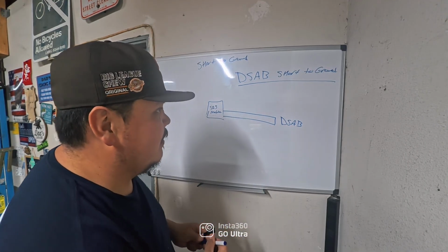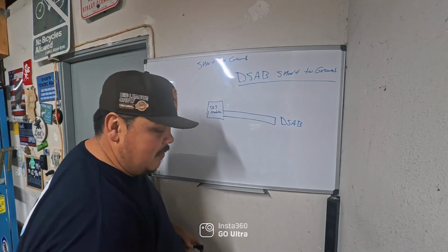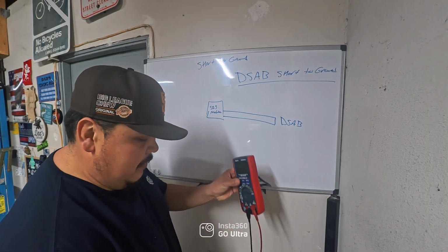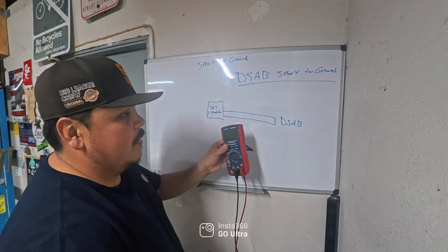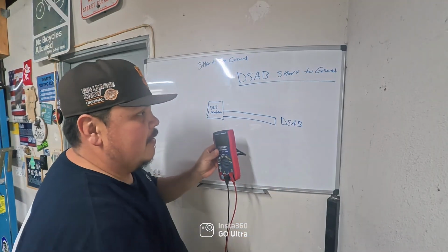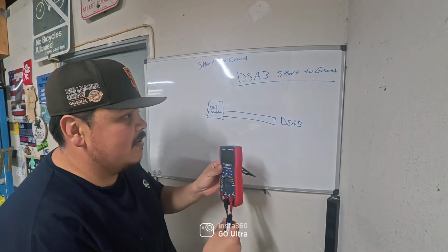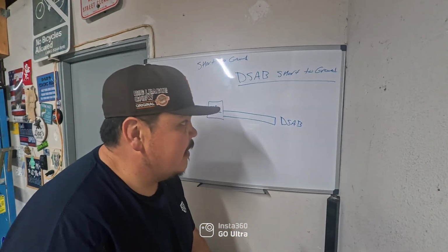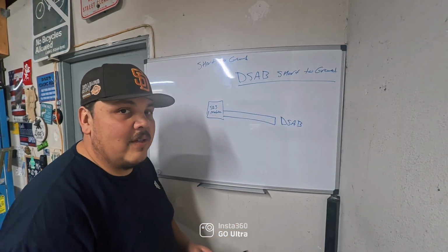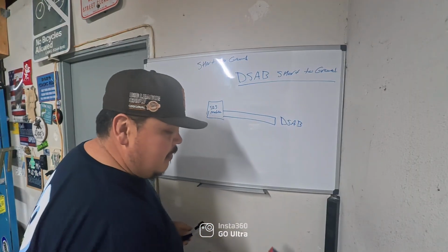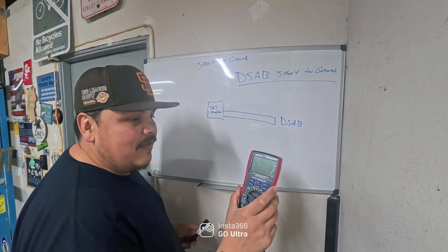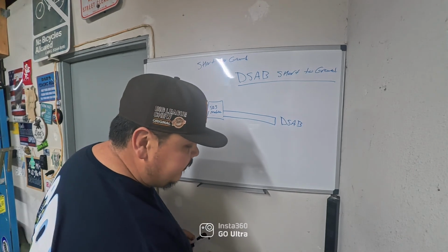What you can't do is grab your meter and start testing voltages and resistance values if both components are plugged in, or else you're going to set it off. The voltage inside of the meter is enough to set off airbags.